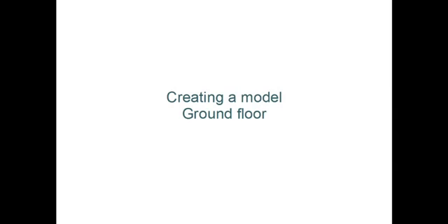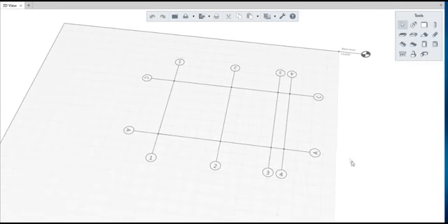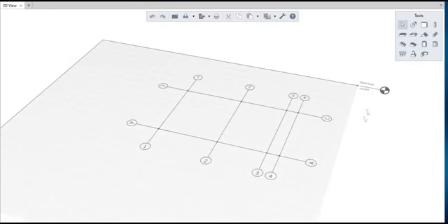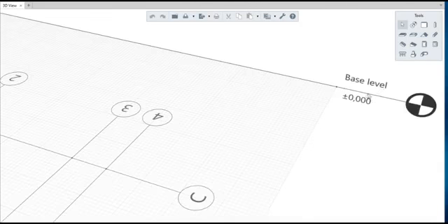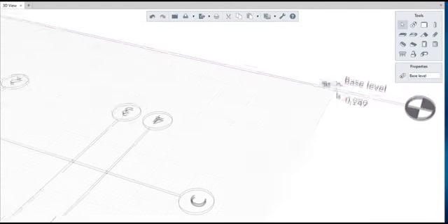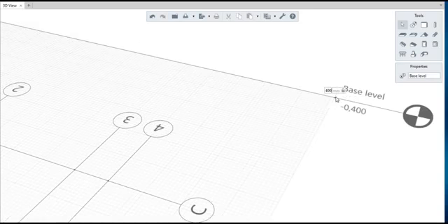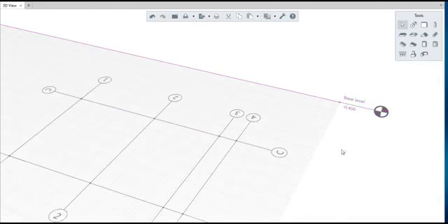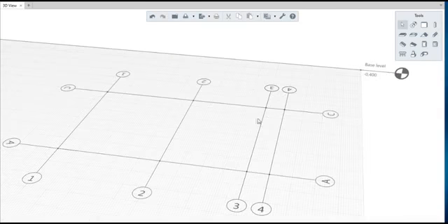In this second tutorial, I show you how to create the ground floor of the townhouse and then start on building walls. But first, we need to move the work plane down by 400 mm, to the level of -0.4 meters in the ground level. Select base level and then, holding down the Ctrl key, move the plane by the point on the level with 400 mm as vertical offset.